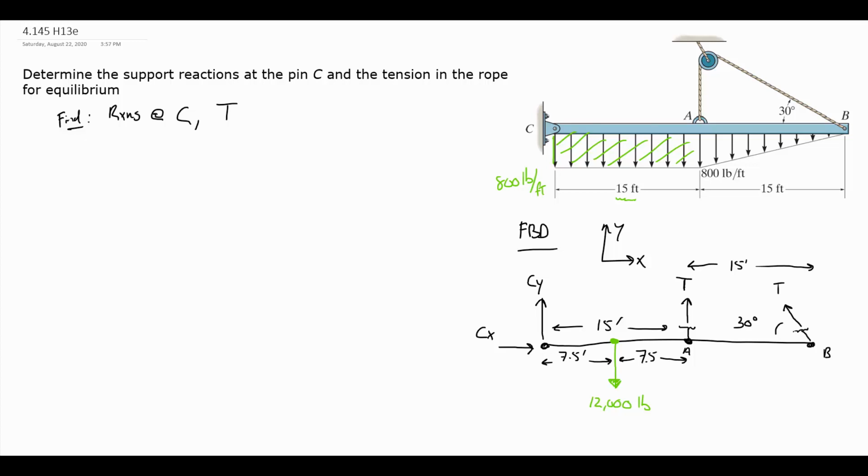So I know where I'm putting the point load and the value of it. I've simplified the rectangular load into this equivalent point load, and now it looks like something we've been analyzing with 2D rigid body problems. Now I can go on and look at the triangular part of the load. And again, I'm going to do that as its own calculation instead of trying to put both point loads into one.